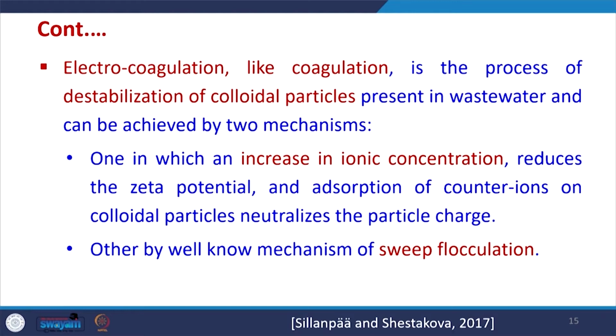Many colloidal particles first destabilize, so their charge will get reduced. If we are providing enough mixing, different colloidal particles may come together and form flocs, and these flocs may settle down. So, using the in situ coagulants which are generated, the colloidal particles are destabilized in the water.